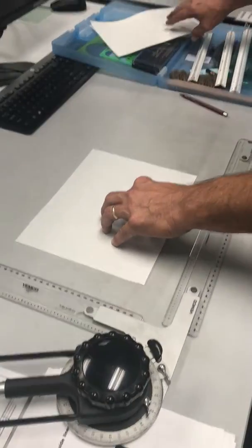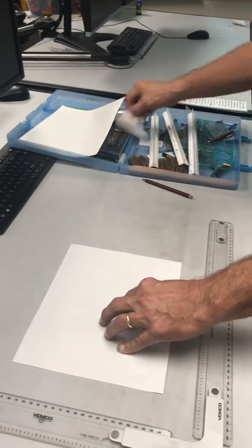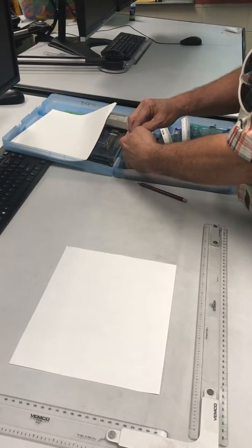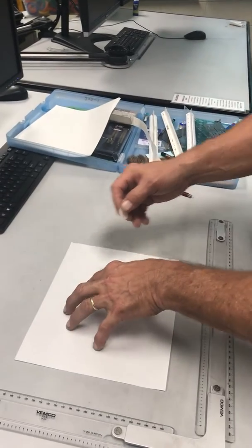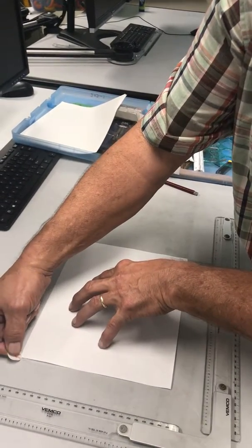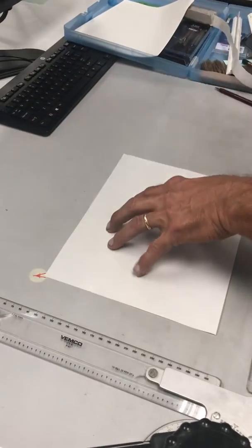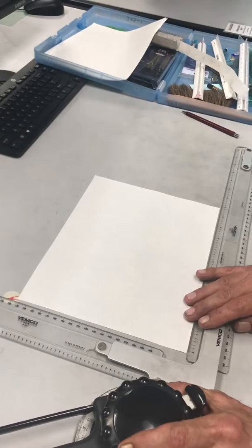And then here's our kit right here. Guys, you should have drafting tape for your kit. And inside your drafting kit, you're going to take this tape and you're going to hold down your first corner right here. Make sure you don't cover too much of it up because you've got to do title block lines. So let's do one there. And let's just recheck to make sure we're square.